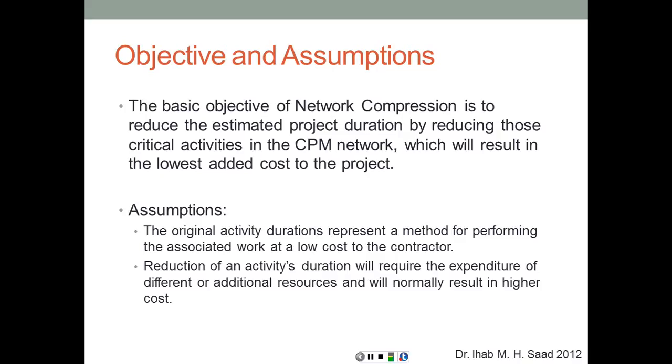Some of the assumptions: the original activity durations represent a method for performing the associated work at a low cost to the contractor, and the reduction of an activity's duration will require the expenditure of different or additional resources and will normally result in higher direct cost. Higher direct cost, which is the cost of the additional resources that you're going to need to utilize, again, labor, material, equipment, subcontractors.